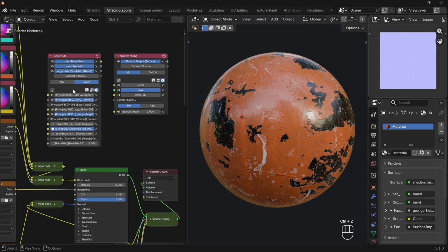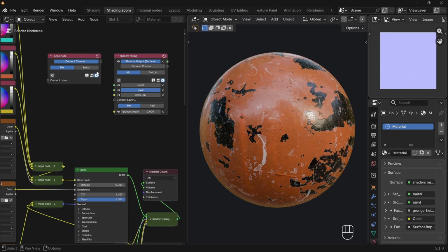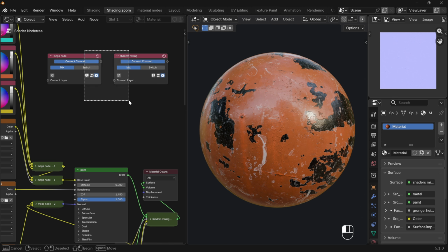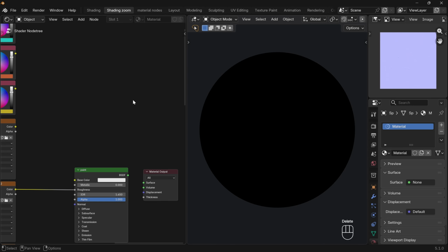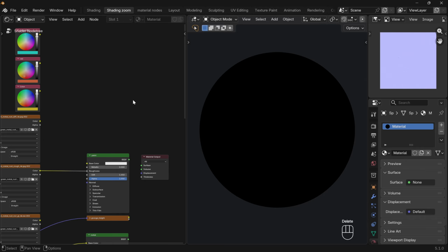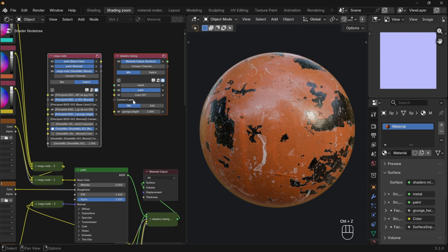If we want to delete a ShadeMix node entirely while leaving their background setups intact, we can use Ctrl-Shift-Click on a channel. The Ctrl removes all channels, while the Shift safely leaves their background setups intact. Or just Shift-Click for a single channel node, and we can select and delete them without losing its setup. However, if we simply select the ShadeMix nodes and delete them directly, it will also delete the background group nodes they control, completely removing the setup. You can see all these shortcut combinations by hovering over the info icon.